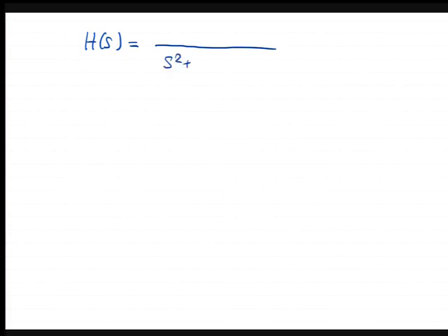But the poles of the second-order polynomial will not depend in a pretty way on these two coefficients. A better parameterization that gives us where exactly the poles are is the following. That looks weird at first sight, but you have to get used to it. 2 times zeta is a parameter, omega n is another parameter, times s plus omega n squared.